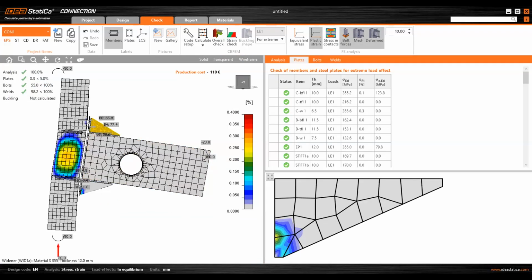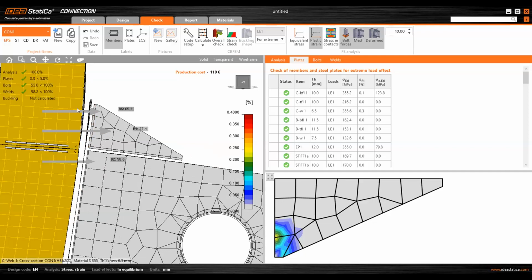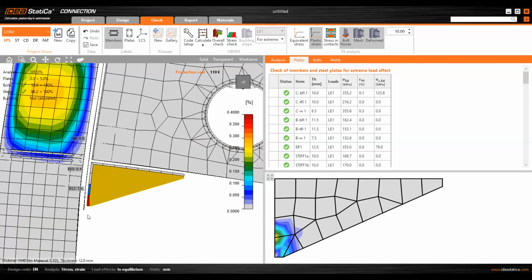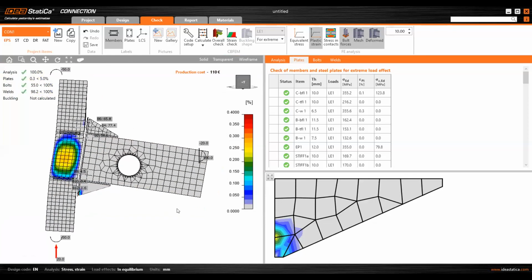This is how it is bent. And of course the forces in those top bolts are much higher than in the lower bolts. But still there is some action there because of what is called in Eurocode prying forces, which appear in the bolts not because of the tension but because of the deformation of the plates. Additional forces appear.